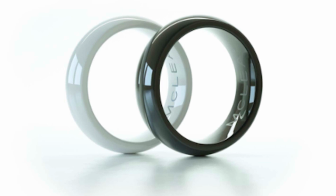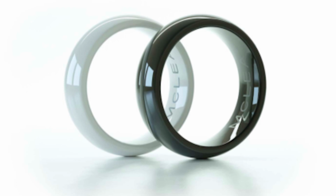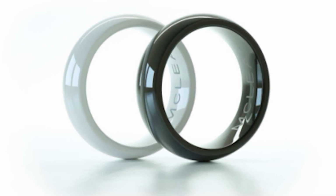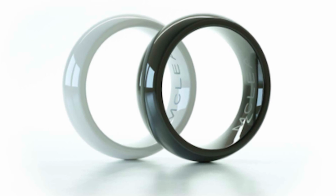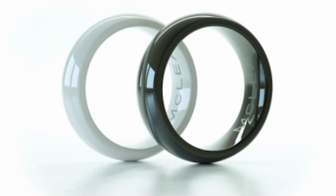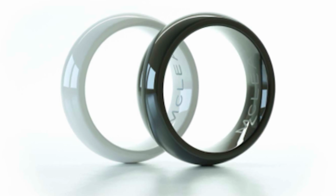One of the main features of the smart rings is to serve as a near field communication, that is NFC, device, effectively eliminating the need to carry credit cards, key doors, and car keys, and potentially even ID cards or a driver's license. So let us understand more about NFC. NFC, or near field communication, is a set of communication protocols for communication between two electronic devices over a distance of 4 centimeters or less.